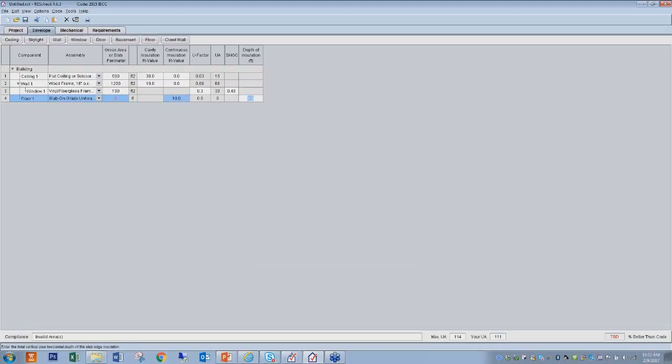And I'm done. Now, down at the very bottom, this is a quick addition I've been missing. I guess I got to put the slab footage in, right? This is the only assembly, and this is the same in COMcheck, that you would enter in linear feet. I see it quite a bit in projects where they've entered the total square footage for that slab on grade, and their project's failing by 200+%, especially on commercial buildings. Linear feet, you're adding up the linear feet. Go around the building only of the addition and add up that linear feet of the edge of the slab.